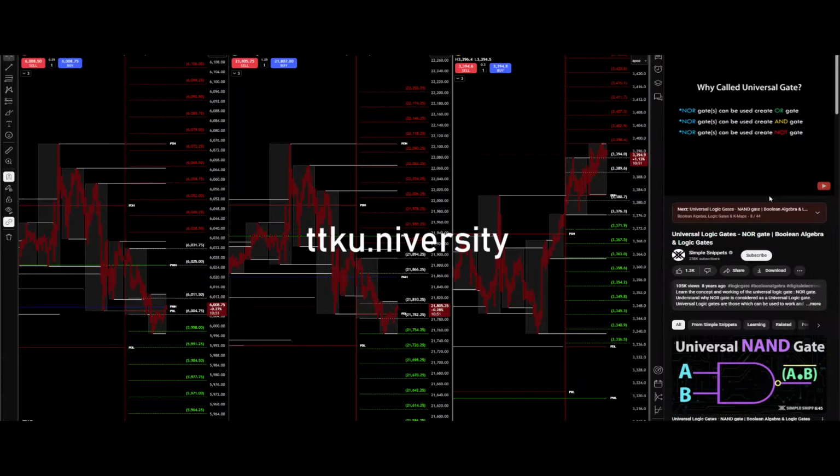So let's see how this is achieved in real time, wherein I'll show you on the screen and we'll prove the derivations as well. Okay, so as you can see on the screen, I have divided it in three parts. In the first part, we'll be proving the NOR gate to be working as an OR gate. Now we know the OR gate expression is given by Y is equal to A or B, but the NOR gate expression is given by Y is equal to (A or B) the whole complement. So how do we achieve that?